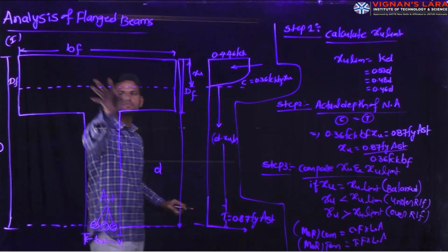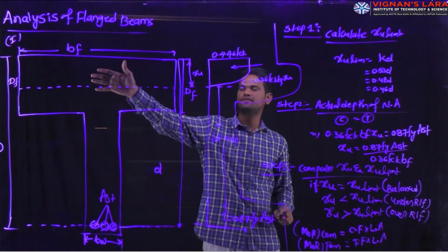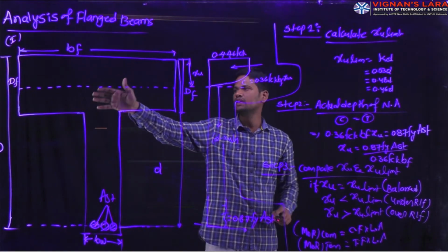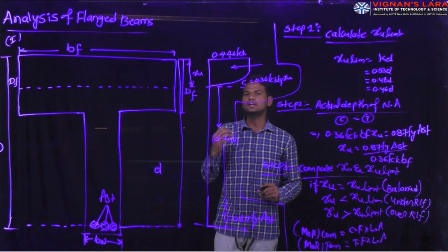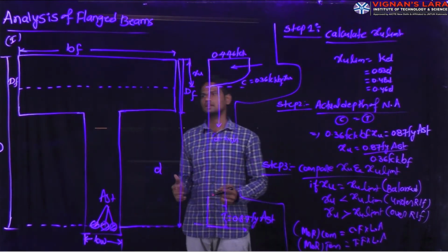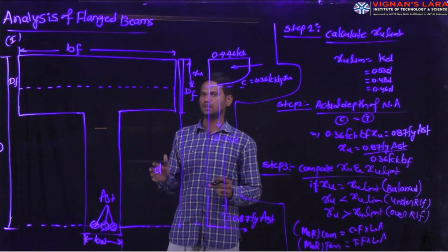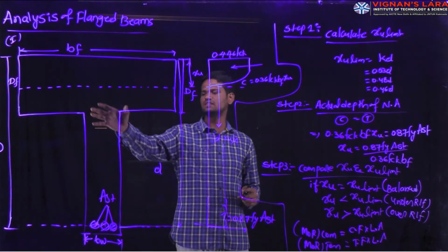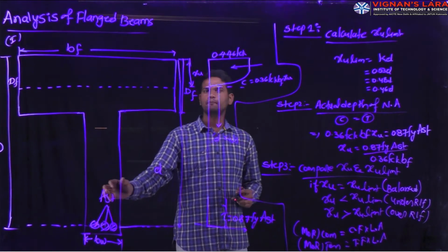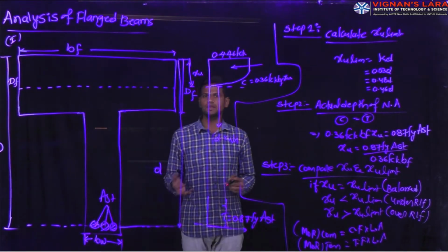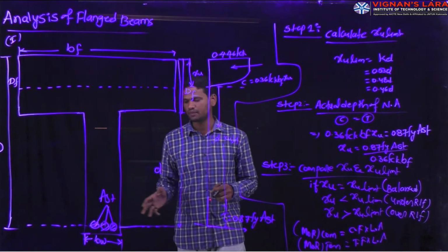On the top side, as already told in the previous class, this portion is called the flange portion or slab portion. In this flange portion, we also provide reinforcement. That reinforcement detail we are not discussing here; it will come in the sixth chapter, in slabs. And here, this is the web portion. In the web portion we provide the steel bars, based on the moment acting on the beam, a number of bars based on our requirement of the cross-sectional diameter of the bar.